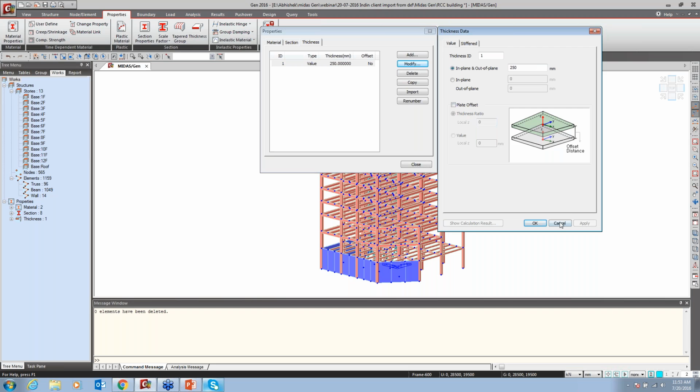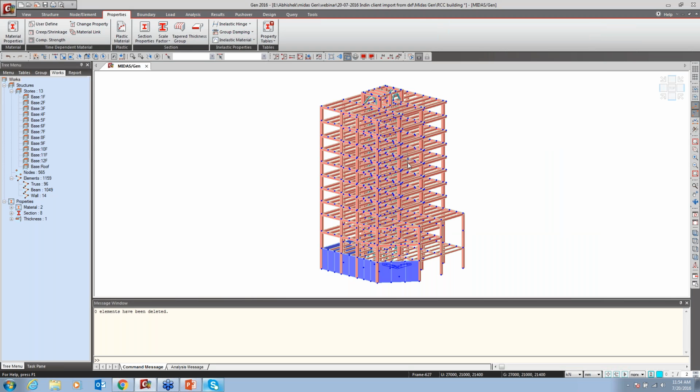So these options are available, and it shows at one level, but it is at another level, especially for a rising floor of 600 plus level. So you can model the slab according to that. Otherwise, if you want, you can model it actually also, but then at the time of defining the floor level you have to be careful. That particular 600 mm level you do not have to consider as a floor. At the time of defining the diaphragm, you can model it accordingly. The connecting member will transfer the load and the moments, but it will not consider any diaphragm.